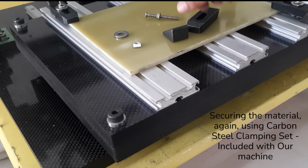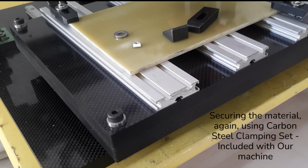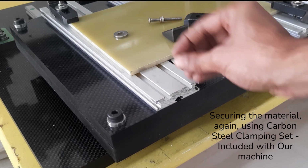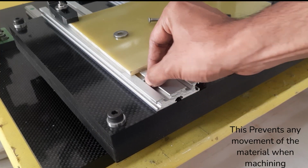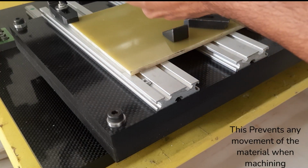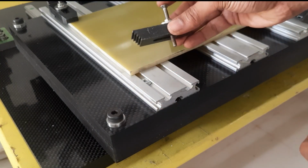Typical clamp installation: you have a T-nut, washer, some kind of a bolt and nut, and then the standard clamps. So you put your T-nut into the rails. Have your washer on top. Put it into your clamp.